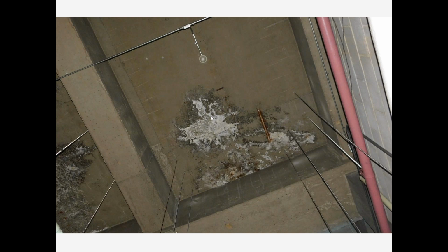We actually went up here, took some samples of this material, looked at it under scanning electron microscopy, and were able to figure out what the elemental composition was. It's essentially sodium and chlorides, so it was salt. Definitely some water infiltration coming through here. You can actually see some water stains on the side of this beam right here, so we know there's some leakage going on here.